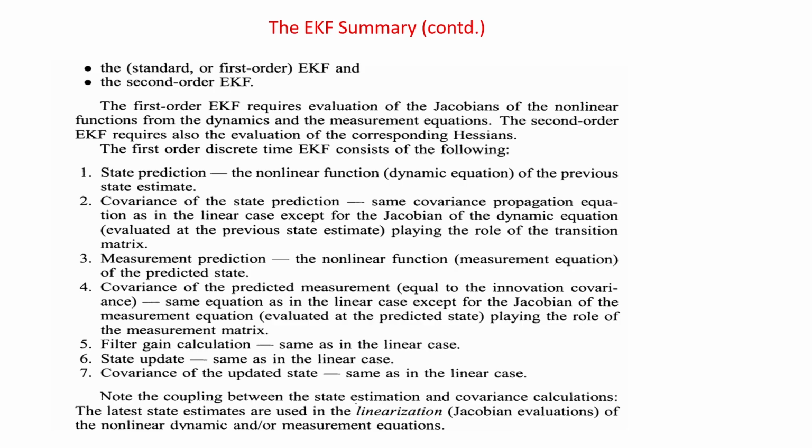Now, you go to your estimation cycle or posterior cycle. Here first you calculate your measurement residual. Residual is your actual measurement minus predicted measurement. Do not use H times x; you should use h as a function of x, the nonlinear function, to calculate your residual, because if you use the linearized function then it will have an error.